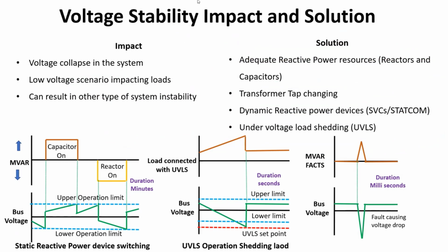There are a few kinds of things that I will tell. You have seen frequency control also, right? You have learned about frequency, that there is primary, secondary, tertiary. There is again a frequency control which is called emergency frequency control. In a generating plant you will see that there is either an over frequency trip or an under frequency trip. It is for protecting the generator itself, right?